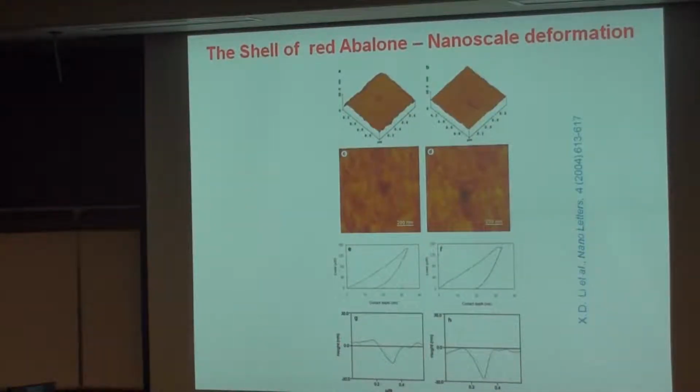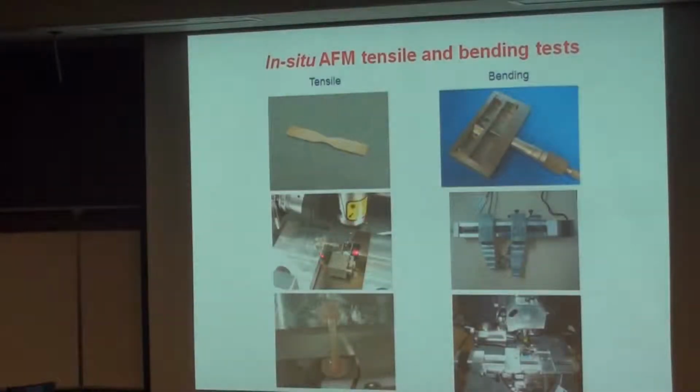And we tried to verify whether those individual bricks are brittle. They are not brittle. So we used a Hysitron indenter on the individual bricks, and we saw piling up around the indentation mark, meaning they are deformable like metals. And then we used this homemade nanomechanical tester integrated with a Dimension 3100 atomic force microscope to fabricate this dog bone-like sample from nacre and perform tensile and bending experiments, without electron beam irradiation.